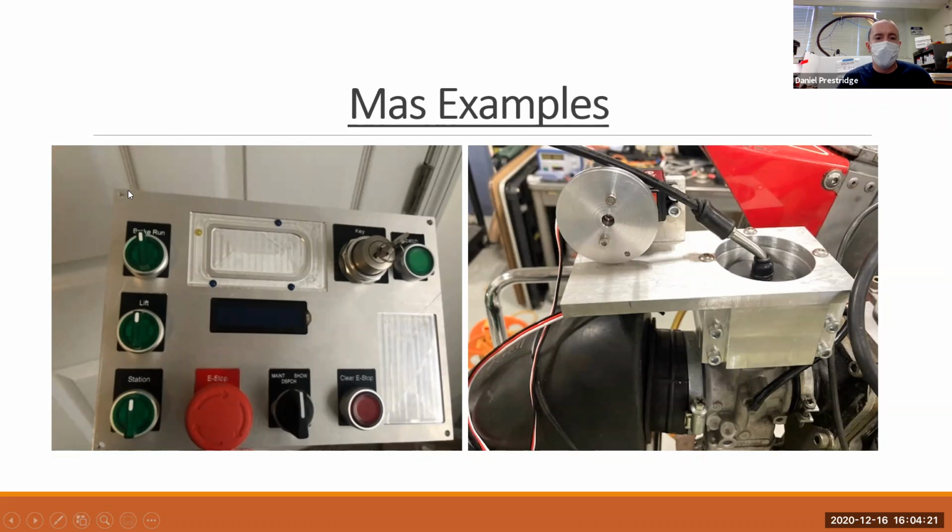So you do your first one, and you do the little holes with that 3.5 millimeter tap drill size, which is going to take a very small bit, could be a drill, could be whatever. And then you want to switch over to the bigger end mill. You have to re-zero for these particular machines because the length is different. So if you tried to just throw a new end mill in there, swap over to the next tool and run it, it would have no idea how tall that end mill was. And it would probably either drive it down into the workpiece or it would just never even cut.